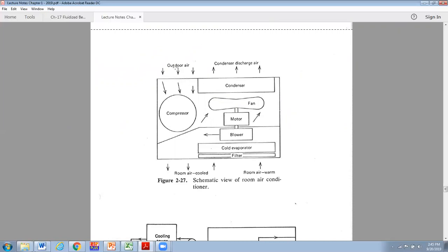This shows outdoor air. I think most of them probably don't really supply outdoor air. I think you can probably buy it if you want to. Be a little concerned that you don't recirculate this hot air back in here. I take it back. That's not for ventilation purposes. I'm sorry, I misconstrued that. That's the air that's going to blow across the condenser. Yeah, you're going to pull it in over here. It's going to help to cool the compressor and the motor here on the fans, and then blow across the condenser coil. Yeah, so you have to have this outside air. I'm sorry, I misspoke there for a second. Apologies.